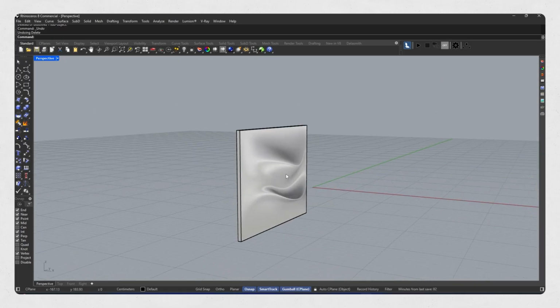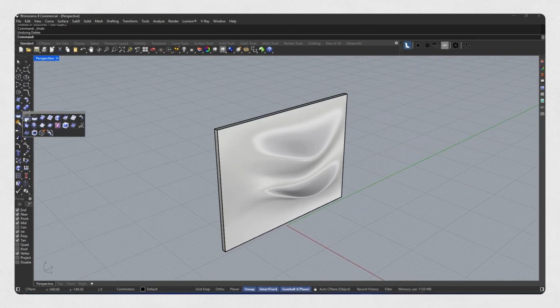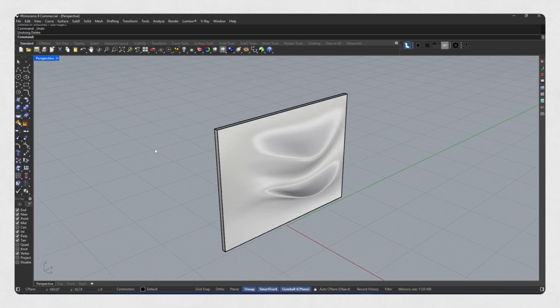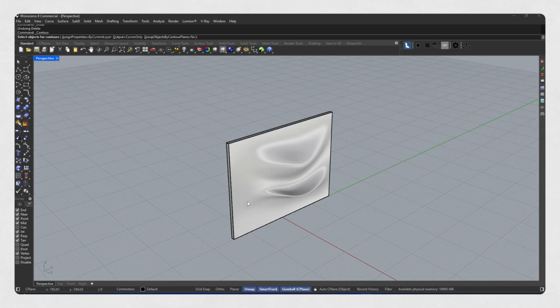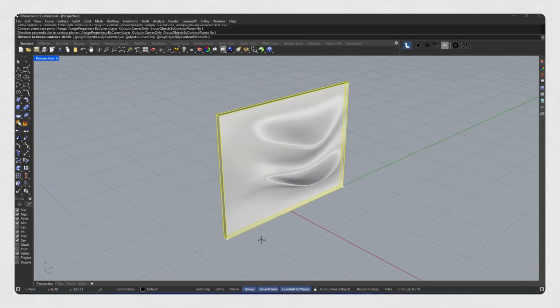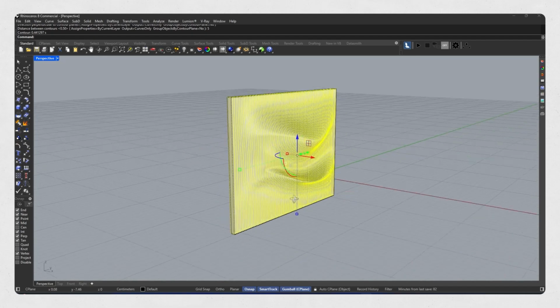Now it's time to do the contouring, right? According to the previous tutorial, I'll drop the link in the description, don't worry. First, we select the object, yeah? Then we execute the contour command. And, oh, we need to specify the cutting directions, right? Super important. And then we got to enter the distance between the contours. Remember that number, because you're going to need it for the thickness too.